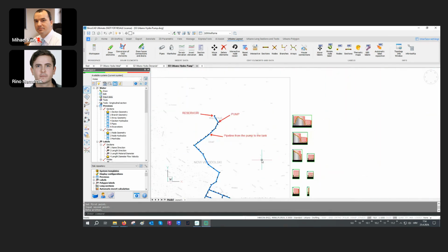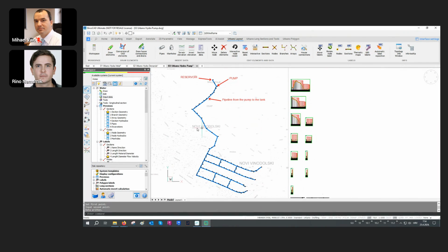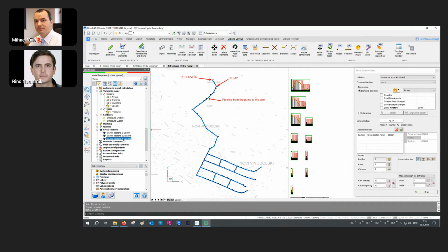This can also be seen very nicely if we draw some cross sections. And to draw cross sections in Softplan is really easy. Basically, just like drawing the profiles, you have your cross section configurations, and everything is stored in those configurations, from scale to colors to data to basically everything. So I will intentionally use this configuration in a little bit larger scale, 40:1.